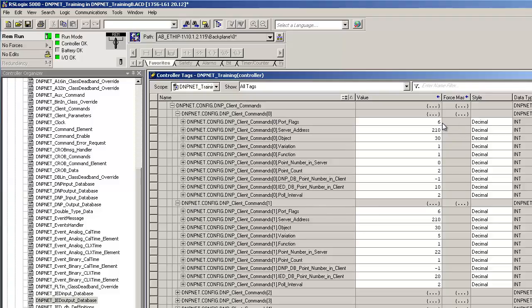Before we proceed, please note that all the analog input data, that is AI16, AI32, floats, and doubles, share a common index in the DNP net, despite the fact that each AI type has its own array. The starting address for one type begins where another type ends. So if your database for 16-bit analog input data is 100, it would go from 0 to 99. Then the database for the 32-bit analog would begin at 100. And if that is sized to 50, then your float data would begin at 150, and so on. This order applies however the databases for each data type are sized.